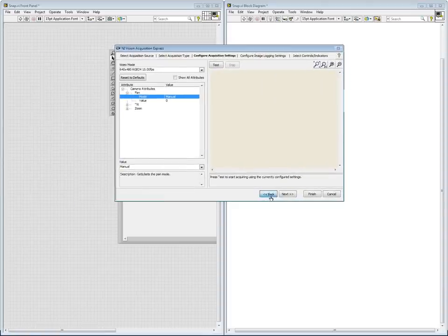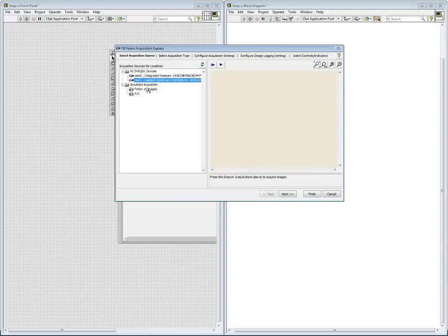Okay. So the dialog box will appear like this. Now the cameras which are interfaced with your system will appear here under IMAQdx. The reason this is appearing under IMAQdx is that when we're using a webcam which is DirectShow compatible, it accesses the IMAQdx drivers. For that reason, these appear across IMAQdx devices.